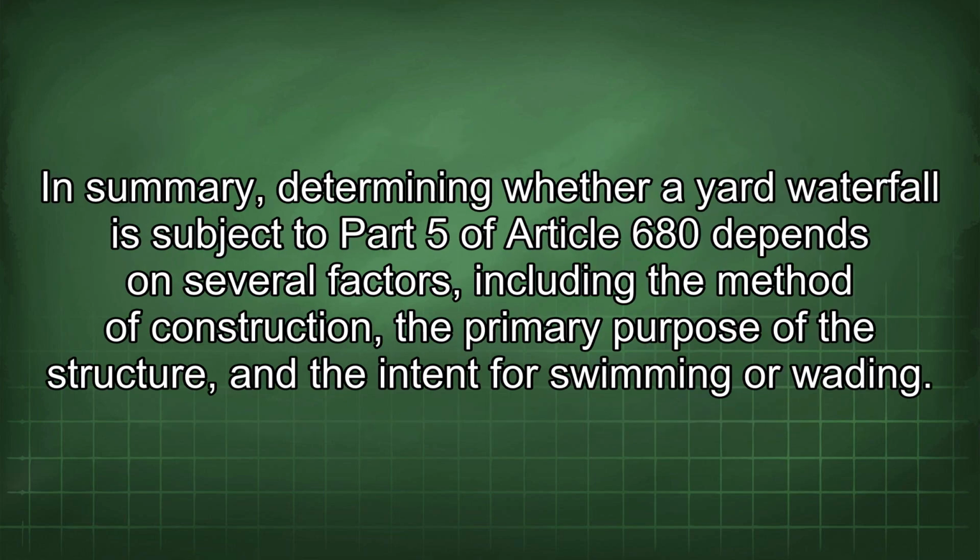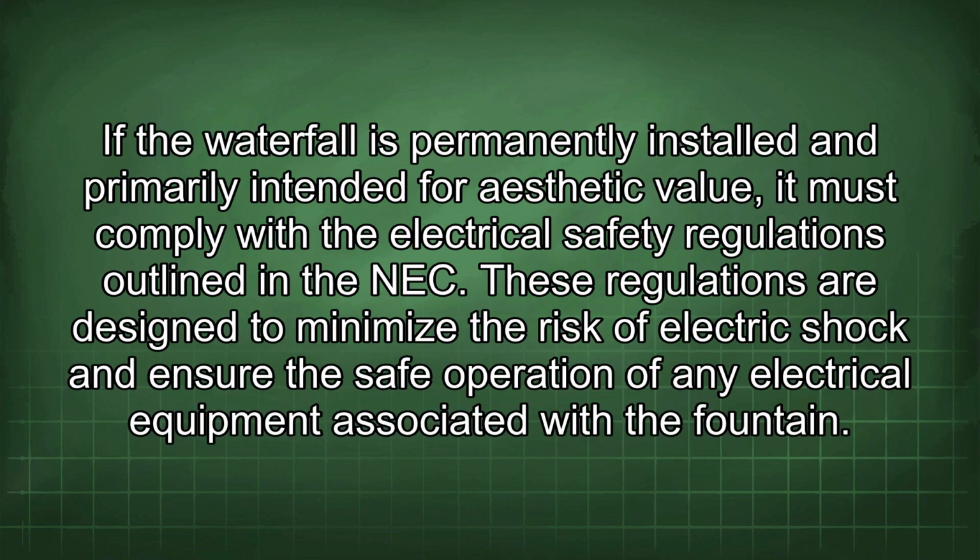In summary, determining whether a yard waterfall is subject to Part 5 of Article 680 depends on several factors, including the method of construction, the primary purpose of the structure, and the intent for swimming or wading. If the waterfall is permanently installed and primarily intended for aesthetic value, it must comply with the electrical safety regulations outlined in the NEC. These regulations are designed to minimize the risk of electric shock and ensure the safe operation of any electrical equipment associated with the fountain.